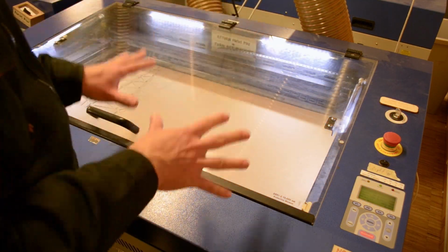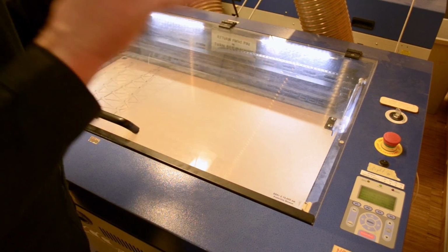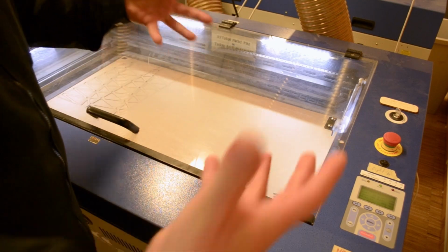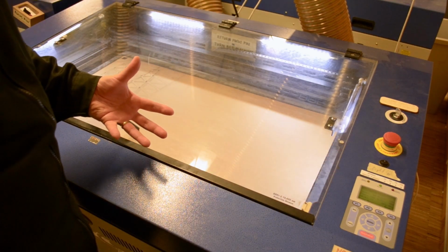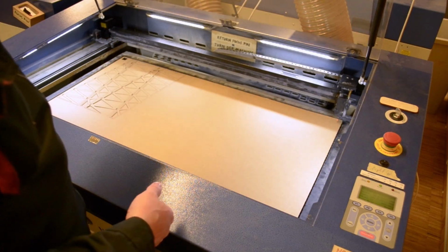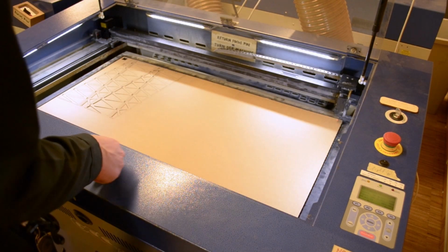If you're cutting any plastic materials, make sure to wait 5 minutes after the beep until you open the glass window to sufficiently ventilate out the nasty smoke. Otherwise, you can open the glass window as soon as the finished beep has sounded.